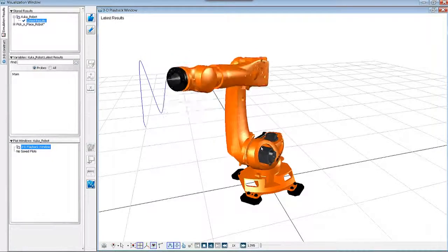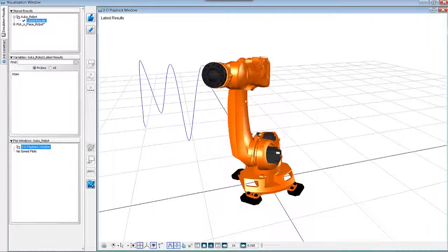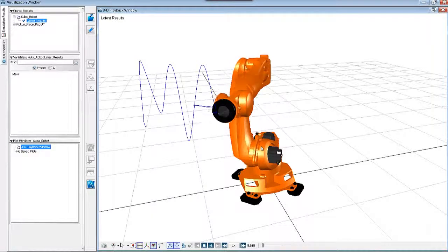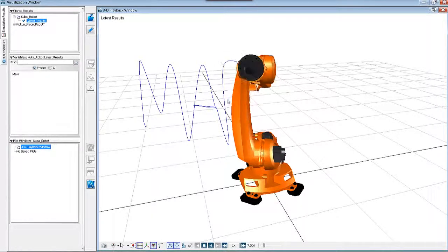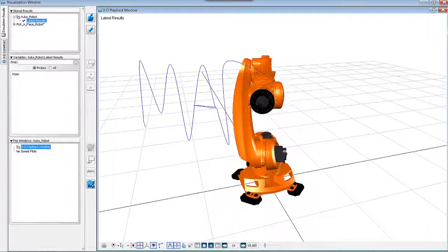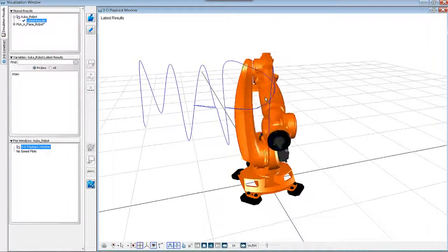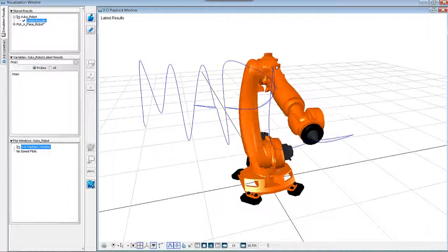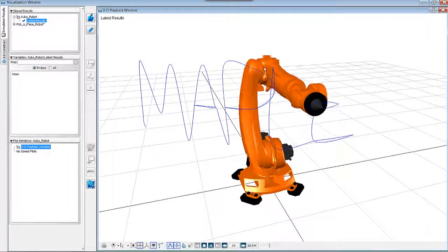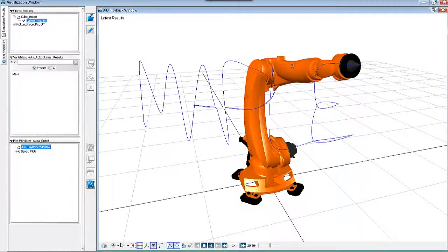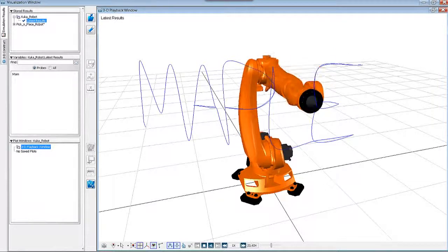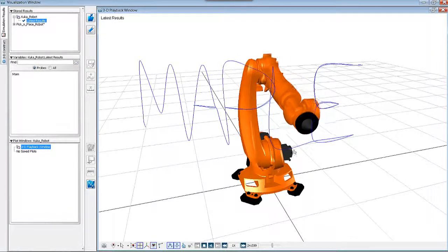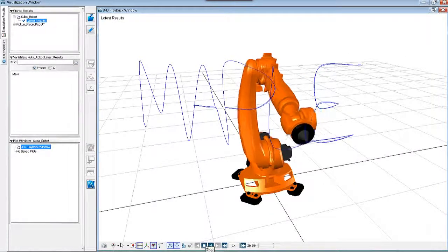Here we can see the simulation of this robot where it's spelling out the word maple, and this is controlled by the end effector location and the inverse kinematics of each of these joints. Additionally, the joints also have a DC permanent magnet motor and controller for each of them to make sure that the motion is as desired. We can take a look at that by going back to the model.